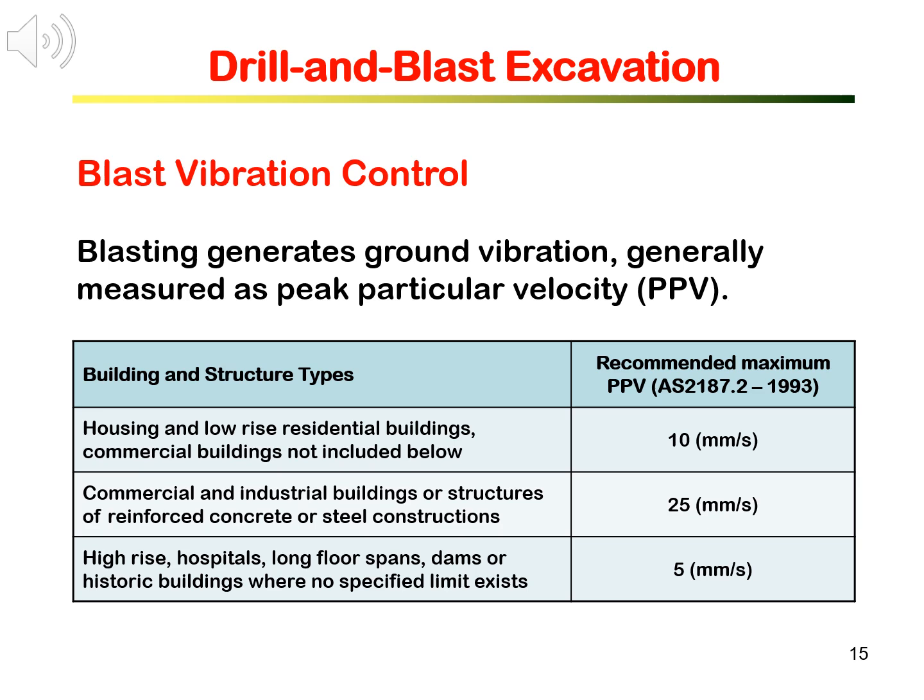Blast vibrations are generally measured as peak particle velocity, PPV. PPV is used as a key parameter to assess building and structure damage due to blasting vibration. The table below is the Australian standard, setting the recommended maximum PPV for building and structure damage control.